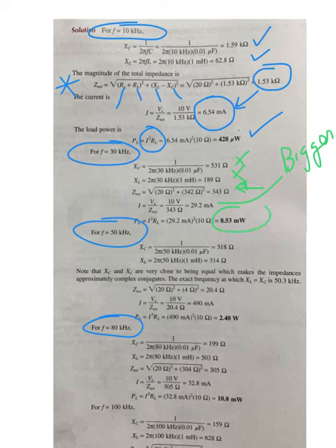It's bigger. It also generates a larger power. Now, I'm not at resonance here. I don't have X sub L and X sub C canceling in either of these. You see, they're not the same value. For the opposite, that just hasn't happened yet until we hit 50 kilohertz.